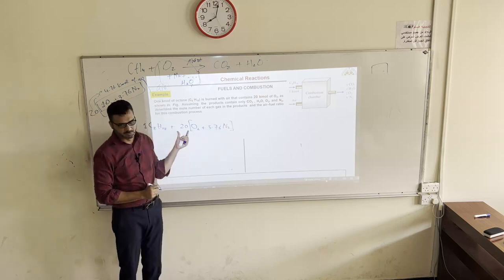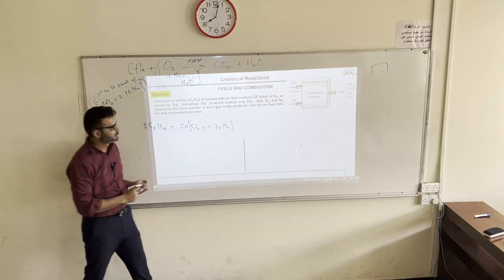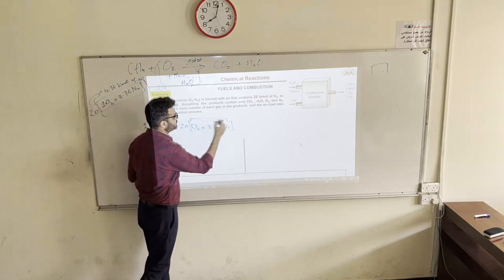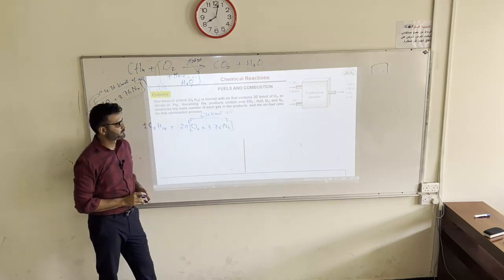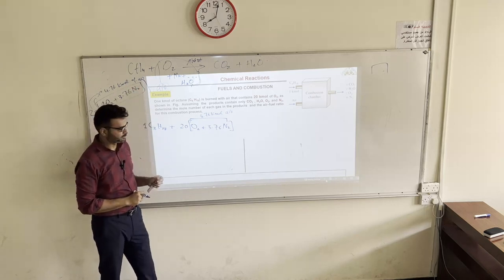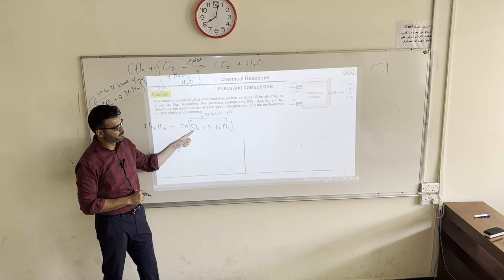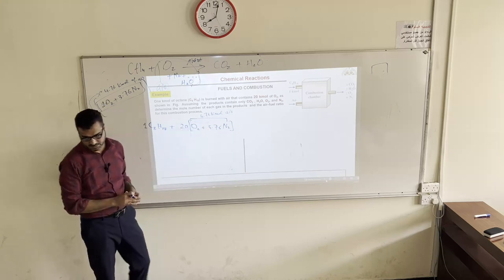So 20 kilomoles of O2 will have 20 into 3.76 kilomoles of nitrogen. And this is 4.76 kilomoles of air. I already explained it to you. So 20 kilomoles of oxygen means 20 into 4.76 kilomoles of air is required.